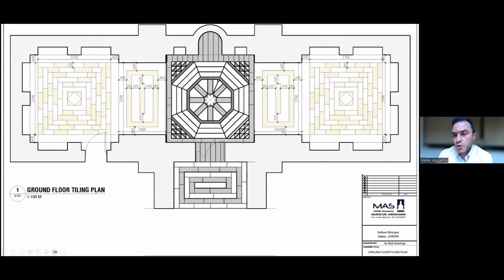It's a very simple mosque. We have three domes. At the center, we have a dome on squinches. Between the domes, there is a vault with a pointed arch, 3/5. And the small domes on the right and the left are shallow domes or sail vaults. The wall thickness is almost 1 meter, so we have these niches to minimize the width of the wall.